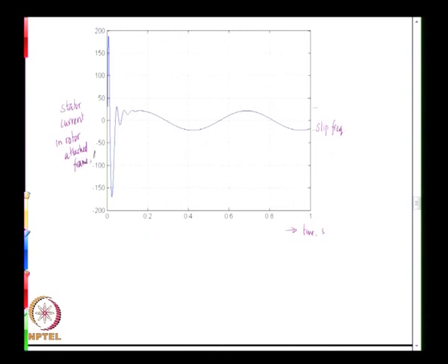So one can by this means transform the machine equations and the responses of the machine to look at the dynamics of the system either completely from the stator side or from the rotor side, whichever is advantageous to the particular problem at hand. One would probably use an appropriate description.